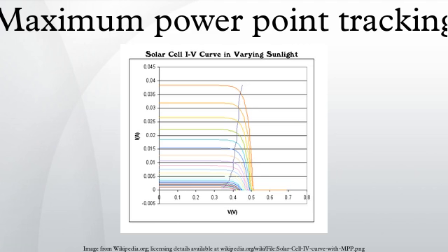When the batteries in an off-grid system are fully charged and PV production exceeds local loads, an MPPT can no longer operate the panel at its maximum power point as the excess power has no load to absorb it. The MPPT must then shift the PV panel operating point away from the peak power point until production exactly matches demand.